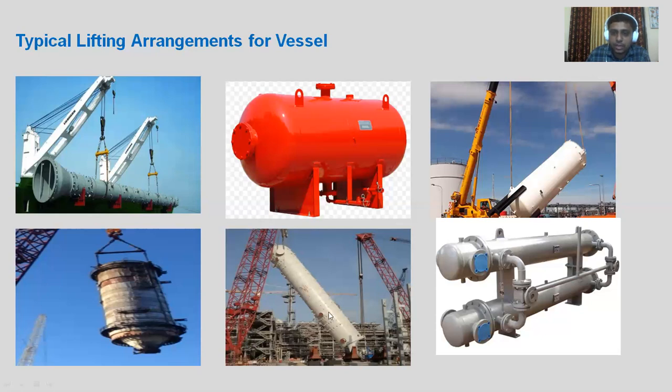So you can see over here in this particular equipment, this is the arrangement by which the equipment will be erected, that is, made vertical. These are nothing but the trunnions. You can see over here, there is a trunnion on this side and another trunnion on the other side, and from that the lifting belt will be positioned. So earlier the equipment was horizontal, and it is then made vertical with the help of these trunnions. And at the bottom you can see over here there is one tailing lug. That tailing lug will be attached with one beam connection like this. There will be a lifting arrangement.